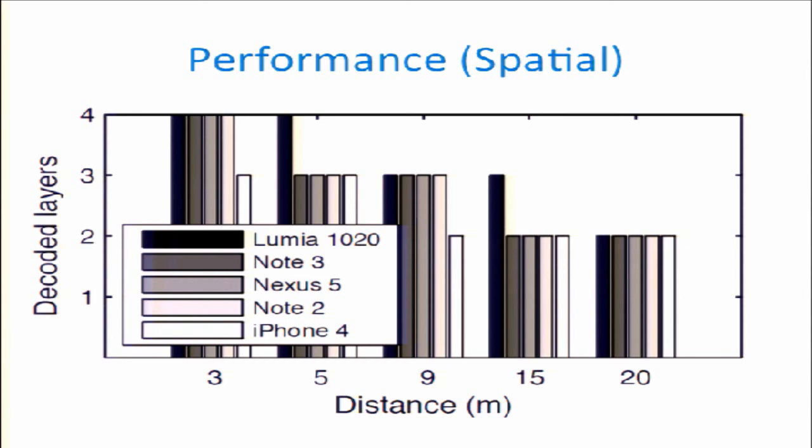Right now, for the experiment, because we didn't have error correction, we do this offline. You decode something and then we compare it offline to the original image. But in practice, what you can do is just add some checksum. So for example, if you decode something and the checksum is right, then you know it's right. These are pretty standard in communication, so we just don't bother. Actually, we played with different variants of this early on, but they didn't add much to what we need to know.